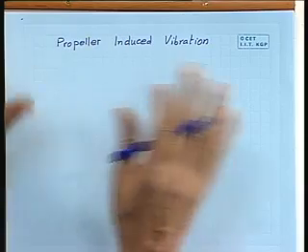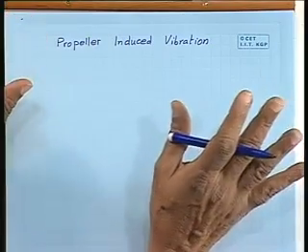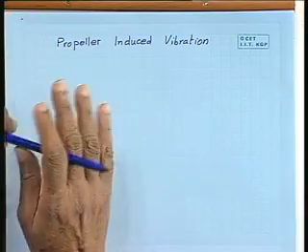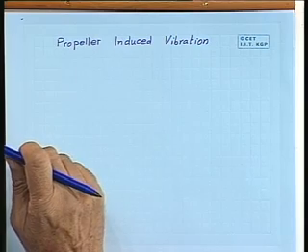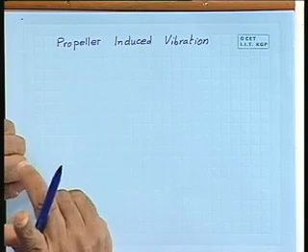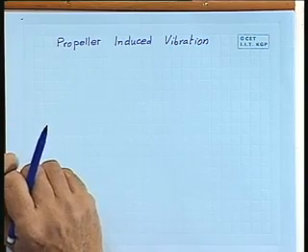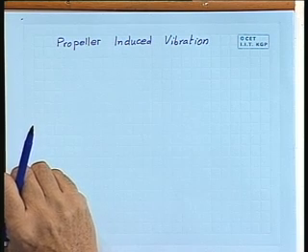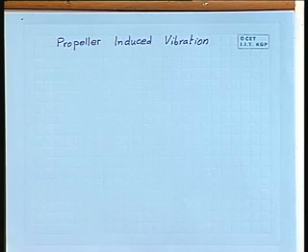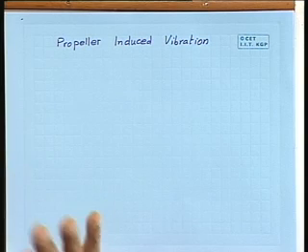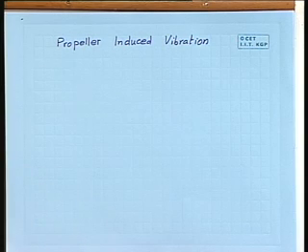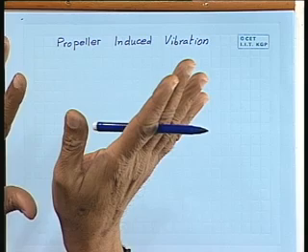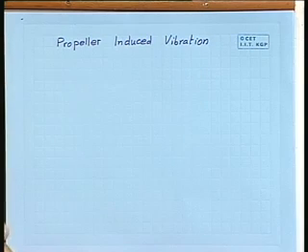The main prime mover is a propeller in a ship, and from maintenance point of view we always try to select a single propeller, and therefore a lot of power is to be transmitted through one single propeller. Usually we have 4-bladed, but there is no restriction on that unless it meets our requirement.